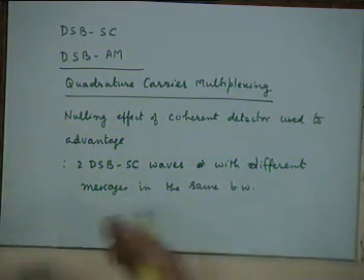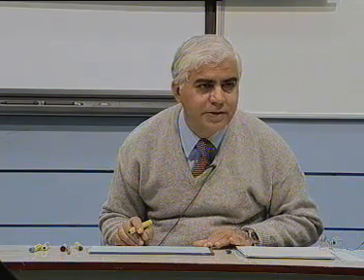The spectral occupancy of both the modulated signals would be in the same fc plus or minus B hertz, right? So if you can do that, what would you do? You would increase your bandwidth efficiency by a factor of 2. In the same bandwidth you were transmitting only one message, now you are transmitting two messages.